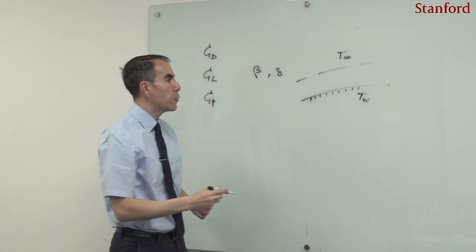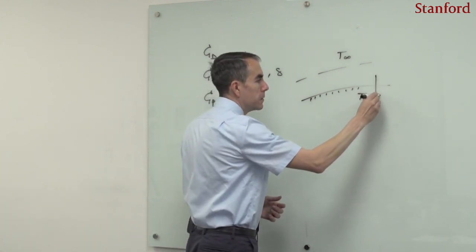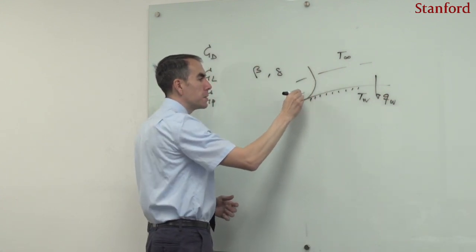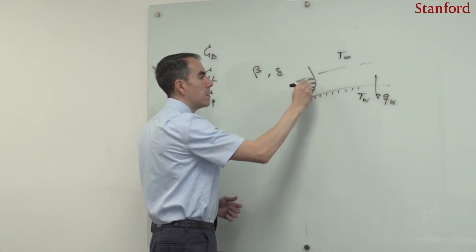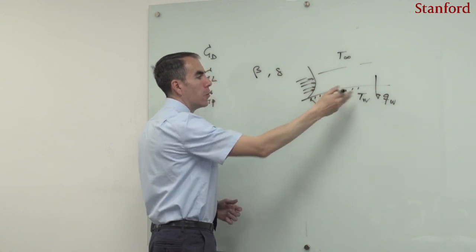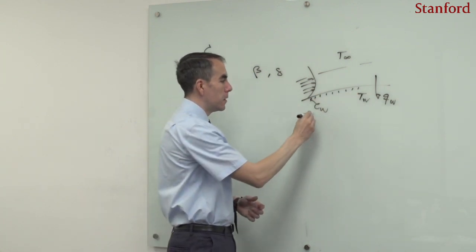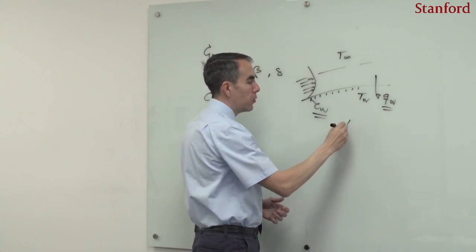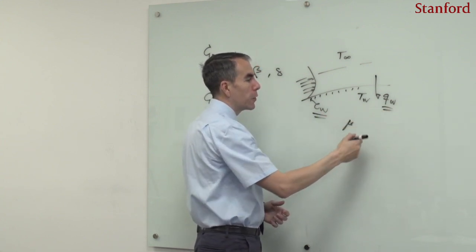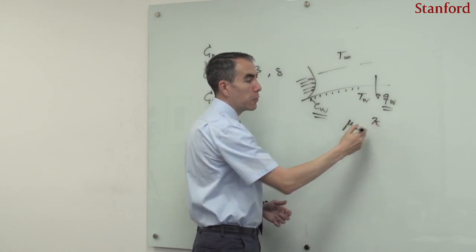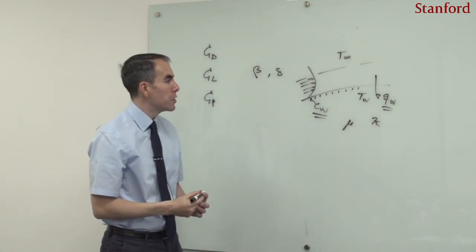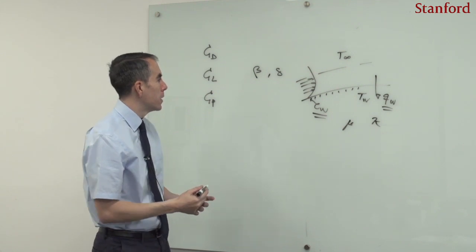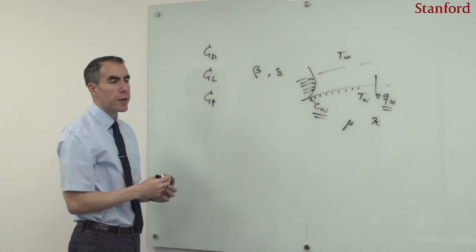In order for us to calculate the heat flux, or for instance to calculate also the shear stress on the wall, these quantities depend on the viscosity for the shear stress and on the thermal conductivity for the heat flux. So one needs to bring the viscosity and the thermal conductivity into the picture, and the inviscid theory is no longer valid.